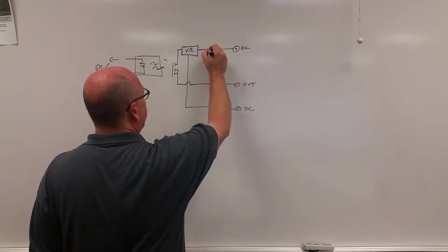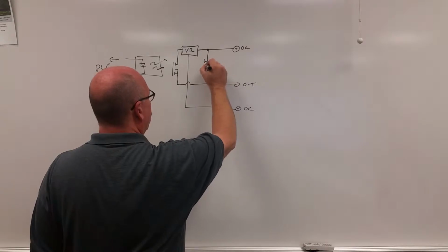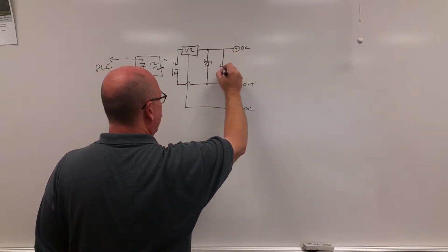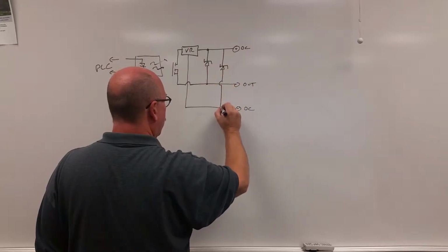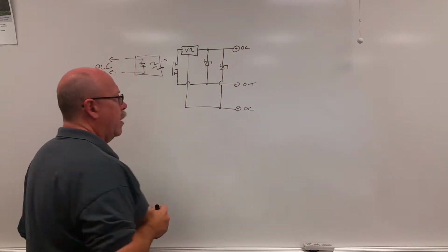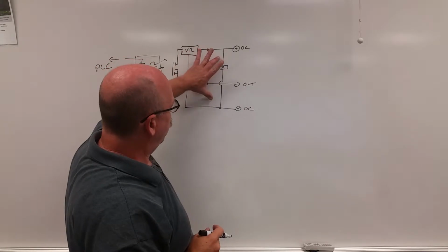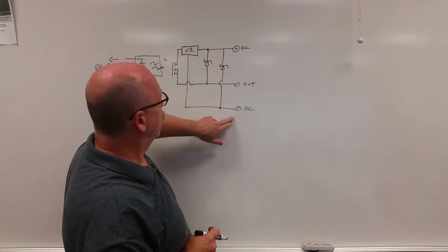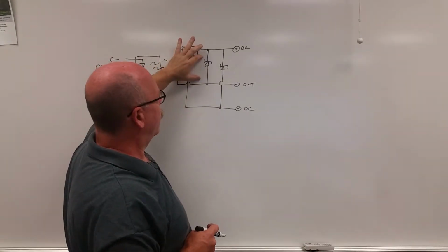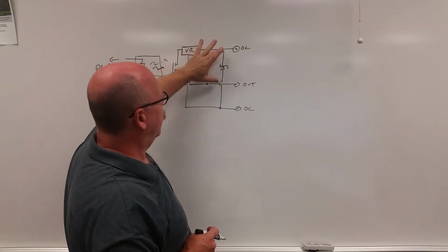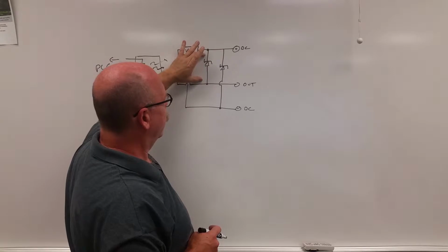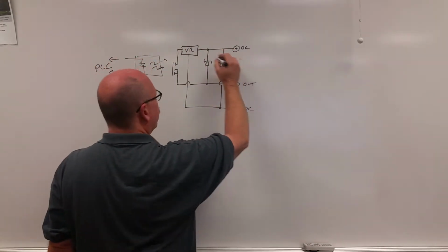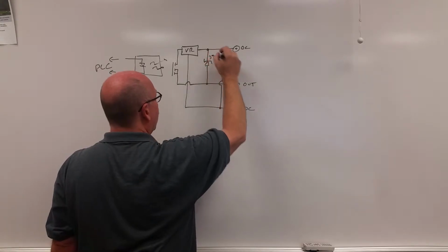Also, inside the output, they have a few Zener diodes. The Zener diodes are to protect from reverse power conditions. And the Zener diode here prevents the output from being reversed and protects the module in that manner. Each of these Zeners, I believe, is about 39 volts.